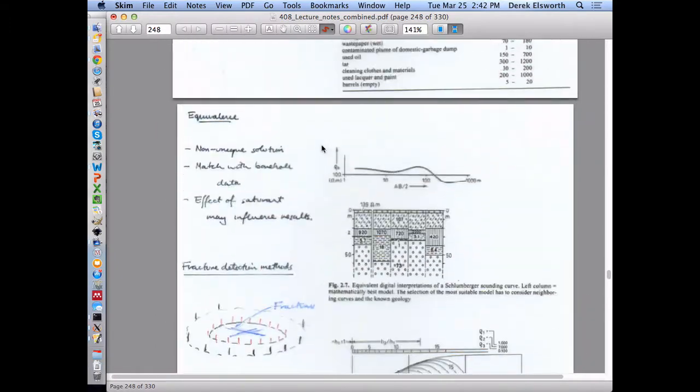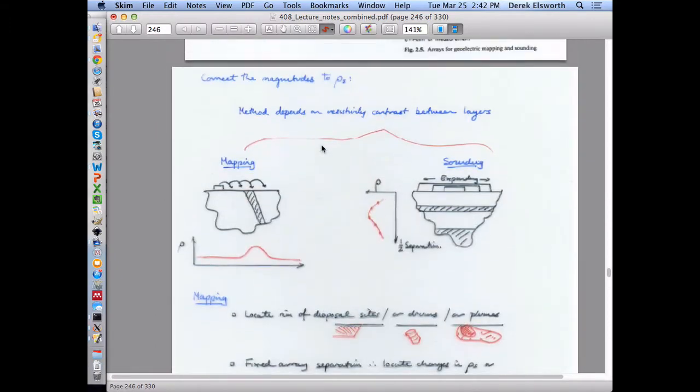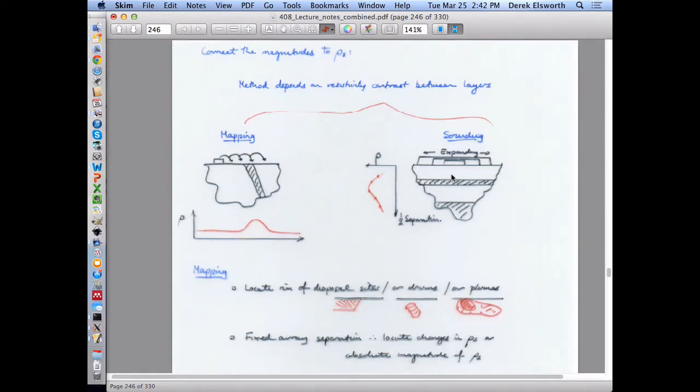We said that they worked in different modes. You could use them in kind of drilling mode by expanding the array and looking progressively deeper. So you have a profile of resistivity that you could check, for instance, against a borehole. And then if you do it at some other location, then you're basically doing another borehole but not drilling a hole to be able to see what's going on. Or you could use them in kind of a profiling mode to be able to take the same array and just transpose it down the pipeline alignment or the road alignment to be able to see if there are any anomalous conditions that you see which would represent maybe something that you'd want to know is there.